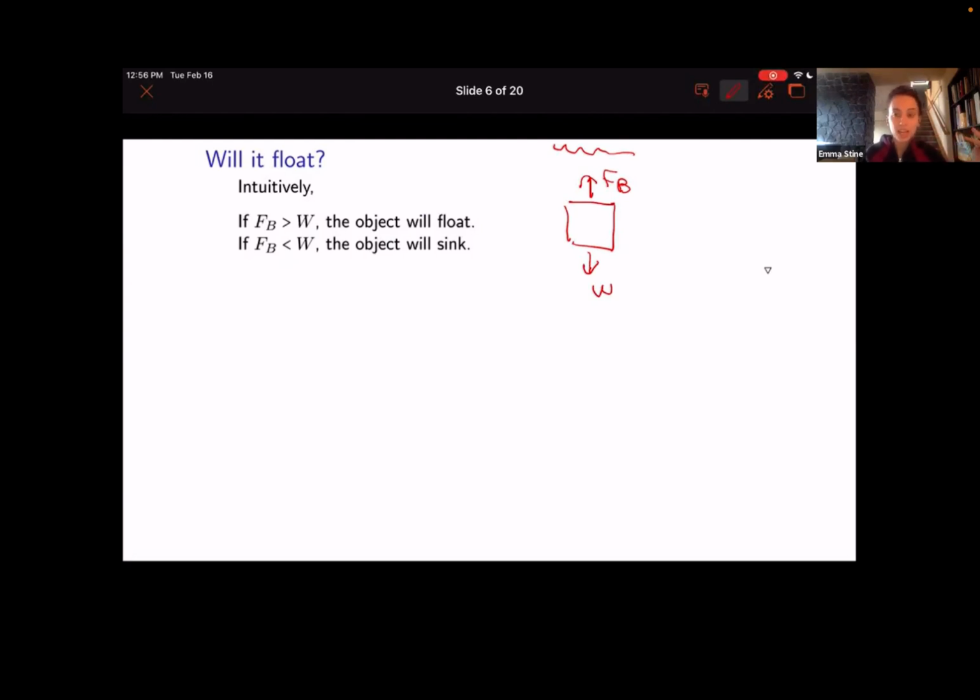And because we just care if it will float, we don't care if this box is partially in water, or fully in water, but because the equation for force buoyancy, the always equation, is specific weight of fluid times volume displaced, and when this thing is fully submerged, the volume displaced is bigger, we're going to think about if it will at least float when it's fully submerged. So we want to care, will this at least float if it's fully submerged, not if it also will float if it's partially submerged.